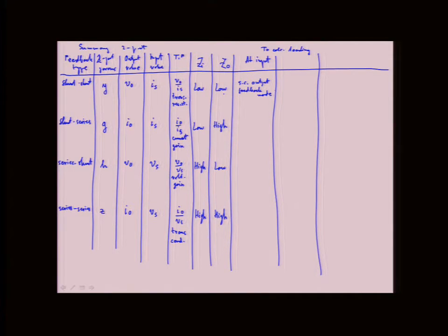Okay, so in shunt-series, what do we do with the output in order to calculate the input loading? Yeah. So we open circuit the output.